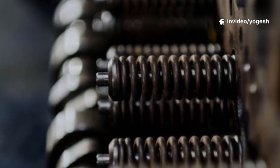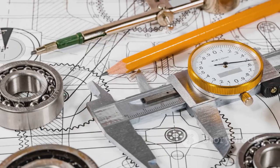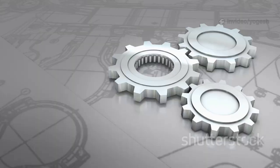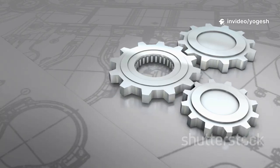Springs are energy masters, found everywhere from pens to trains. They push, pull, and absorb shocks. Use simple schematic symbols in drawings. Detailed helical shapes are for clearance checks only. Include a data table with key dimensions and performance data.